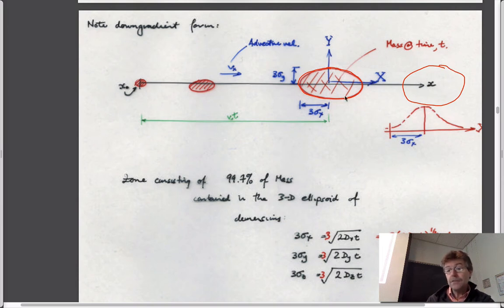To be able to do this, we need to be able to define exactly what the material properties are. So I suppose, without giving anything away for assignments, key properties that would figure into this would be advective velocities. I suppose it would be the time since the release occurred and the advective velocity. And it would be all the components that make up these ensemble dispersion characteristics.